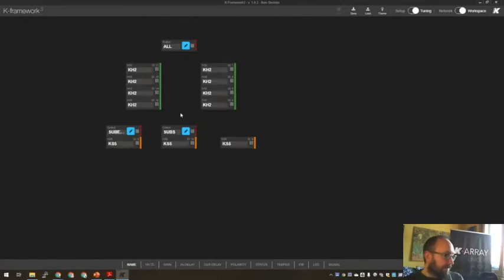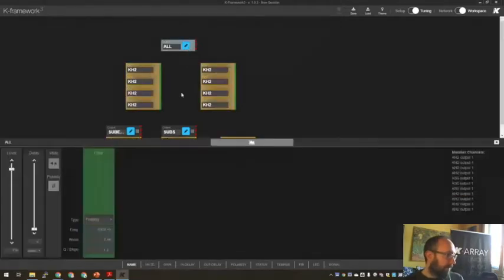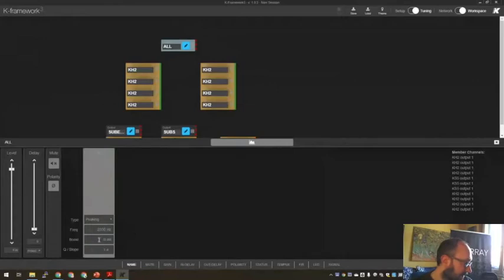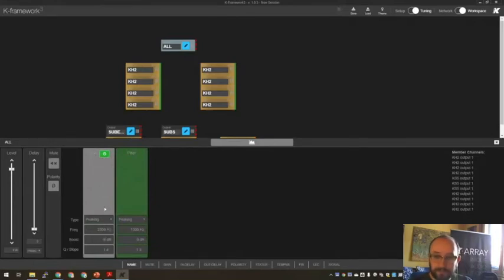Going to play with the groups. So here you have the possibility to EQ specially. Every group is working on the same filter banks of the speakers. So let's say I want to set up a filter like 2500 Hz, minus 9 dB. As soon as I used the first filter, I got another one. I have another one free that I can use to do something else.